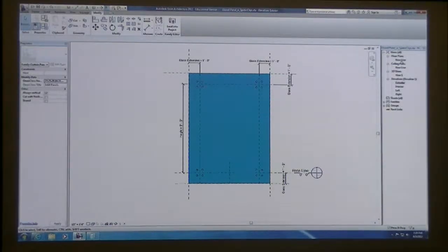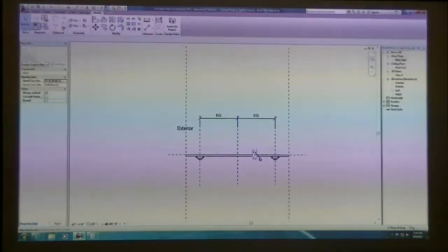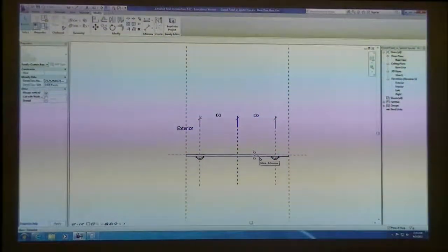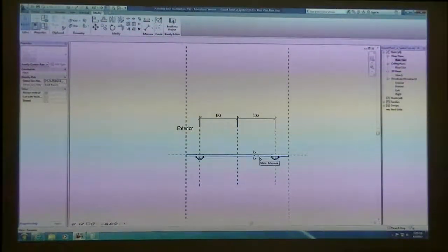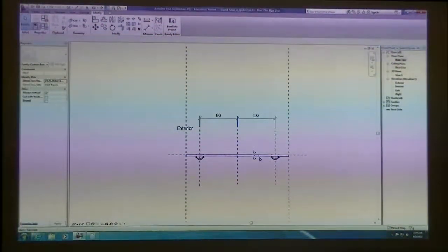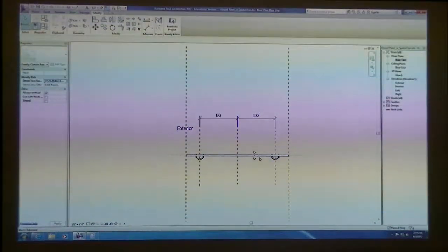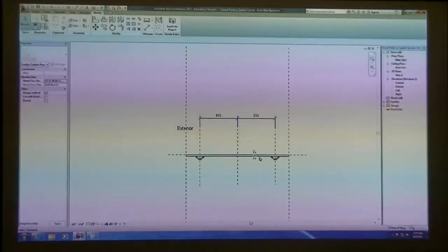Did you edit the sketch? You're in edit sketch mode in the plan view. And if you have remove constraints down at the lower right corner, hit remove constraints. Should be good.